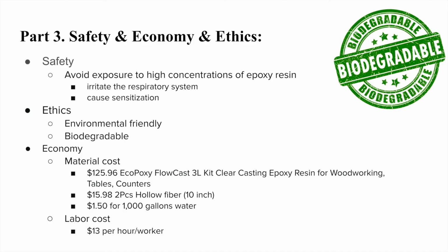For safety considerations, we need to know the physical and chemical properties of the materials that we use. We also need to avoid exposure to high concentrations of epoxy resin. Breathing highly concentrated epoxy vapor can irritate the respiratory system and cause sensitization. When we inhale these dust particles, they become trapped in the mucous lining of our respiratory system, so we need to be careful when we're handling those chemicals.